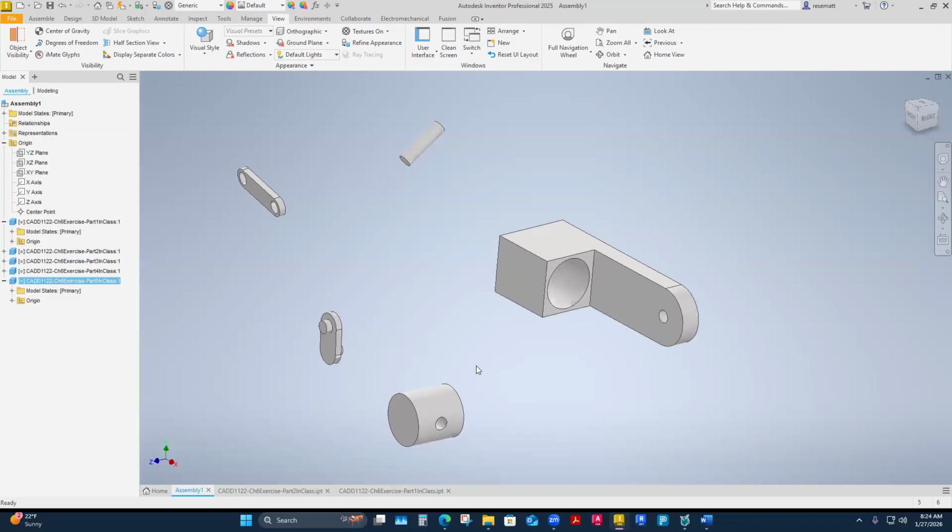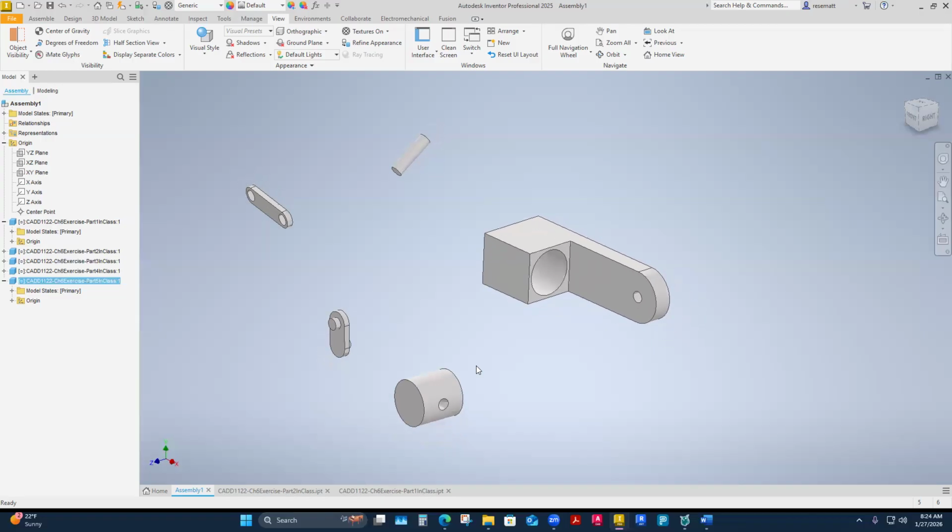And a lot of assemblies have a natural part for that. In this case, the natural part that I can see is the crankcase. And this is because I know the end from the beginning. That makes a difference as well. But this is the crankcase, or the cylinder case, piston case. There we go. And it is going to be the one that I'm going to ground and then assemble the other parts to it.